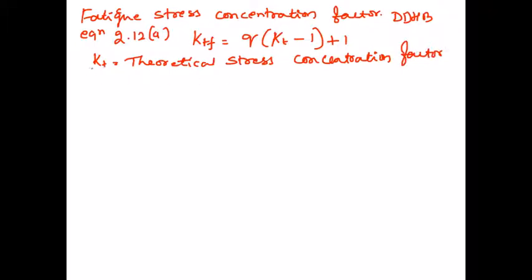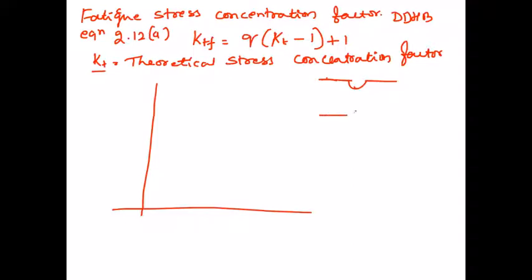So, how to get this theoretical stress concentration factor? So, you refer design data handbook. So, particularly this is a groove shaft subjected to torque. Actually, it has to be circular. Right. So, now refer design data handbook.